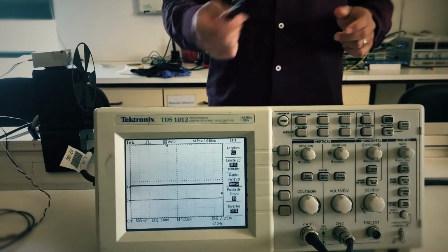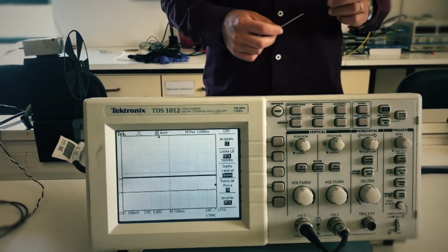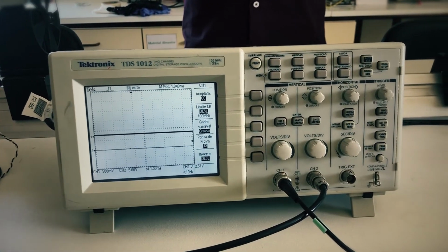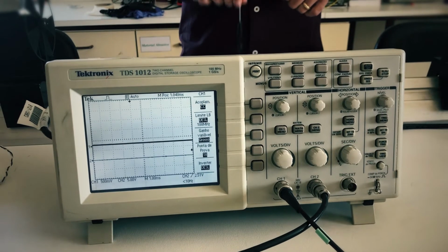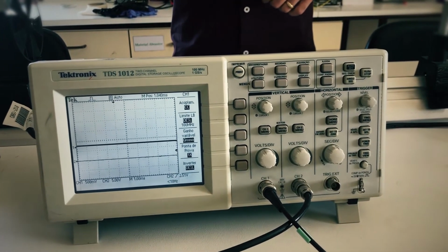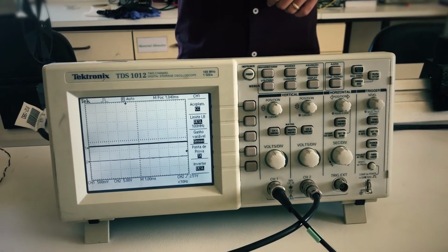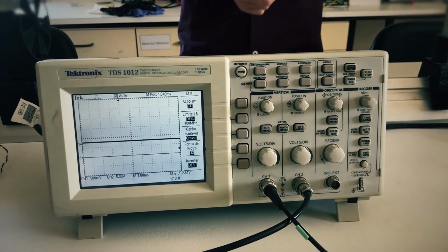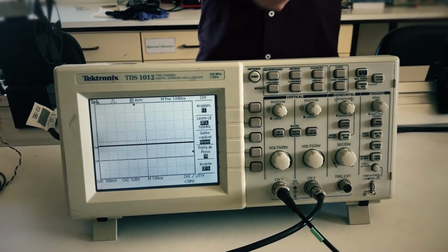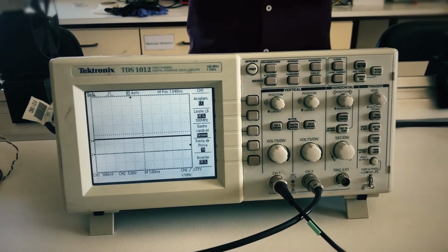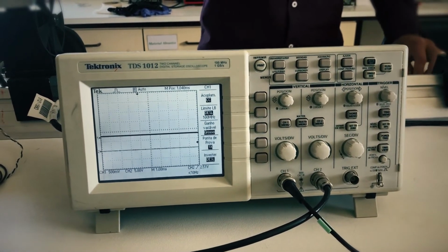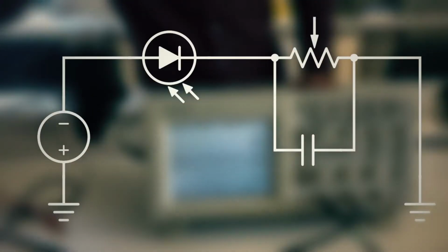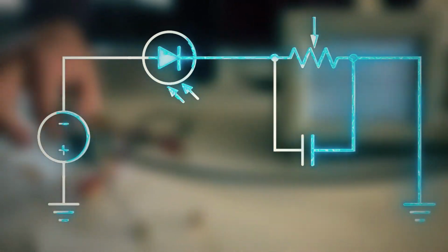This response was observed using an oscilloscope, hence the terminals of the system photodiode plus resistance should also be connected to it. Note that, since a photodiode is a device which generates electrical current when light stimulated, it would be good practice to measure its output current, but since an oscilloscope does not measure current, we observe the device's response in terms of the voltage across the system photodiode plus resistance. This way, the resistor acts as the photodiode's internal resistance, and it is possible to observe its implications. Here, we present a schematic of this assembly.